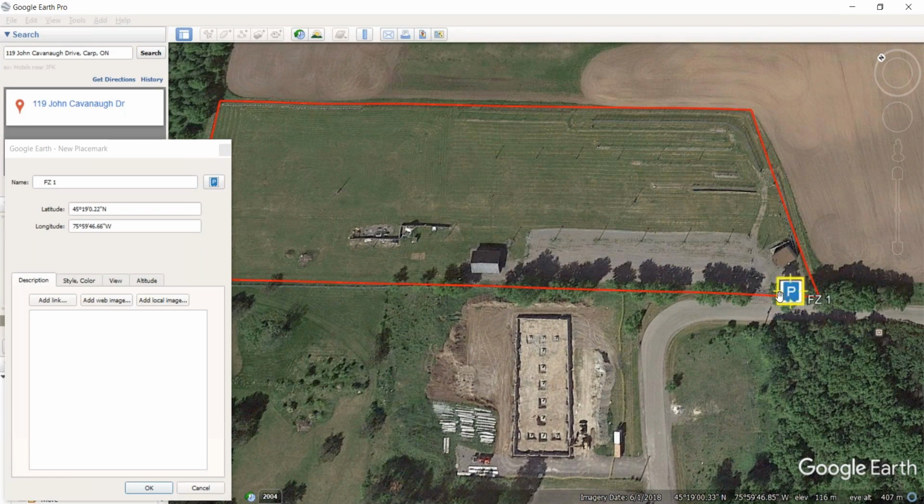Now, some people are wondering, Andrew, why are you going on this side of the gate? And there's a couple different factors. So if I'm looking again at a product specific situation like FlexZone, I know what the capability is of the processor, and I know that I can support 600 meters of cable on one processor, but I have a site that's 800 meters. So I'm going to be going into 2 processors.